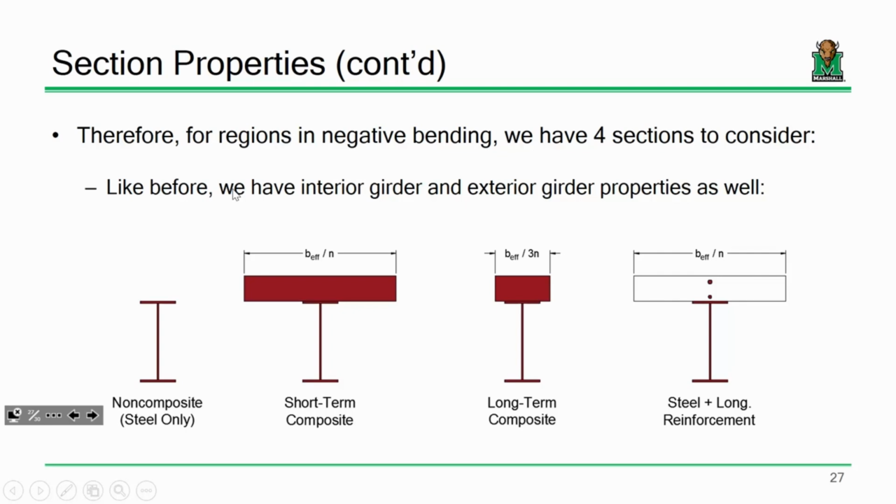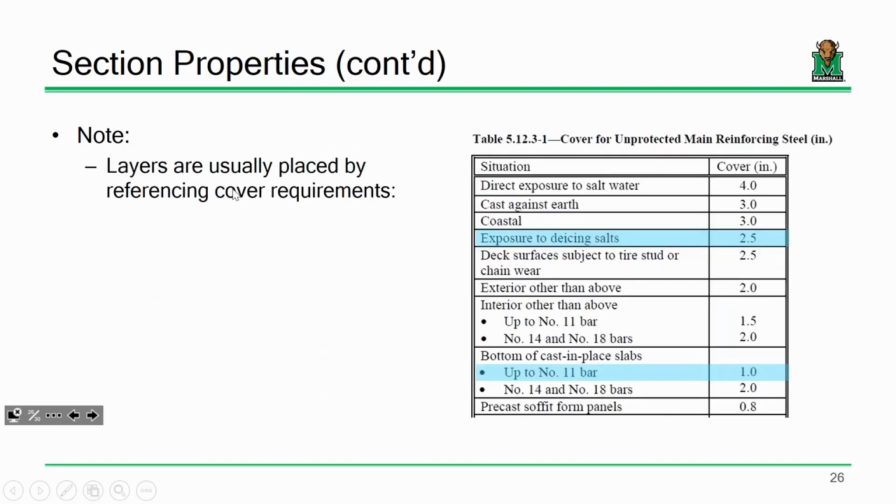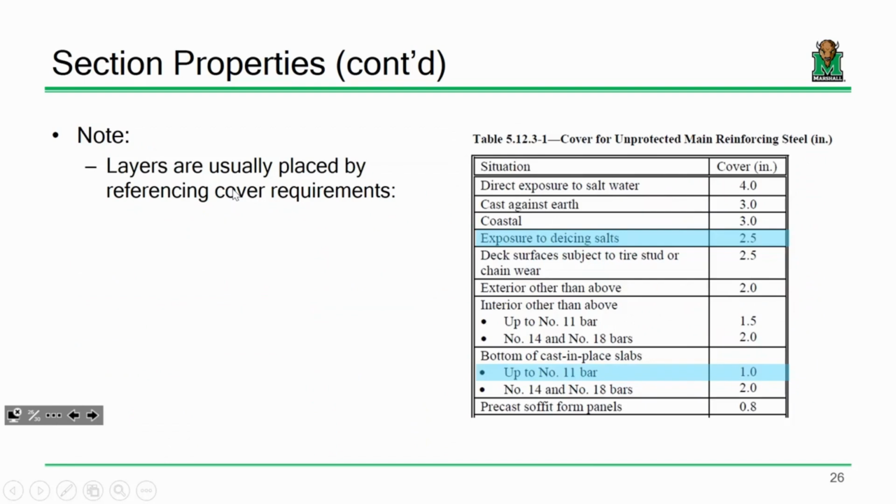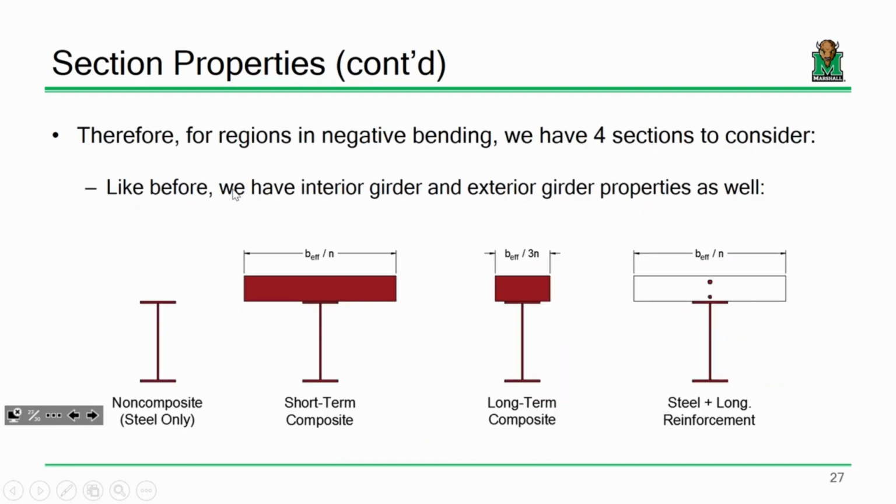Okay? All this rebar, that's 1% of this area. And how do I lump it? All right? 2/3 in the top layer, 1/3 in the bottom layer. So I take all this area, 1%'s all of it, 2/3 goes up here, 1/3 goes down there. That's pretty vague though. What's this whole up there and down there?